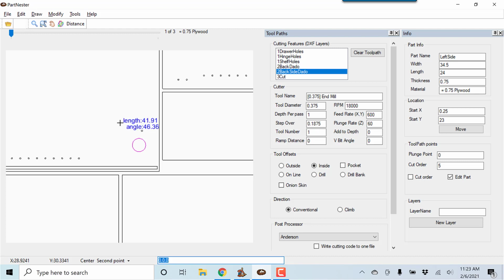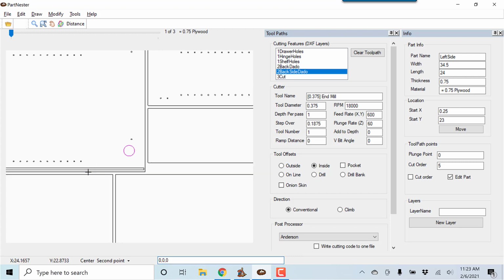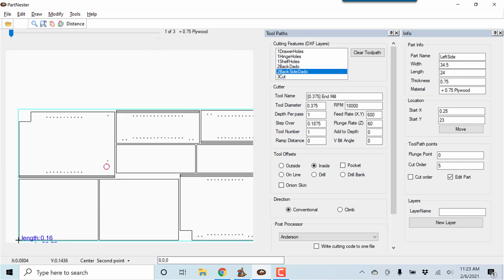That is where I want to move it from, and I want to move it to the location of, and again, that's not moving to, it's moving it relative to the base point that we just created, which is down here in the lower left. Now I'm looking for the next point. I want to move it to 0, 0, because I don't want to move the location of X and Y. I want to have that remain the same place.